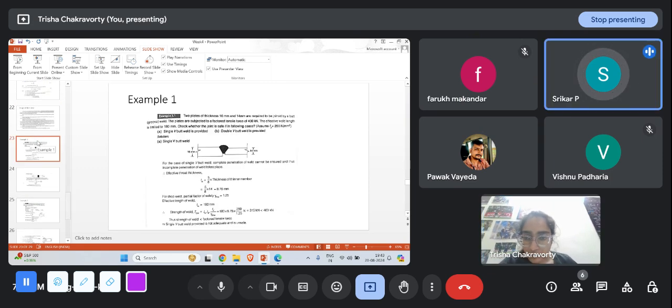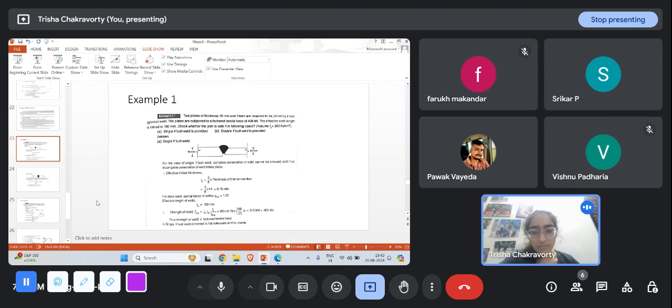Also, one more thing. Will there be any situation where the strength of the welding material, what we are liquefying and keeping there, is lesser compared to the main members? I don't think that is at all possible. Even for bolts, I have never heard of the bolt strength being lesser than the parent material. Because they always say that the connection is the most critical part of the design of a steel structure, so they always try to make the connection stronger than the parent material.